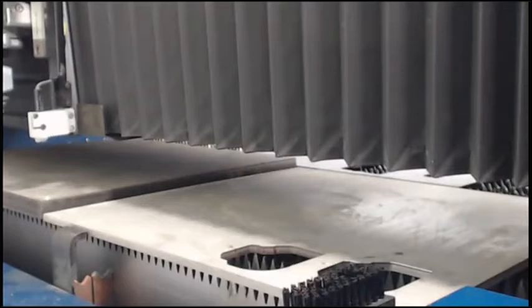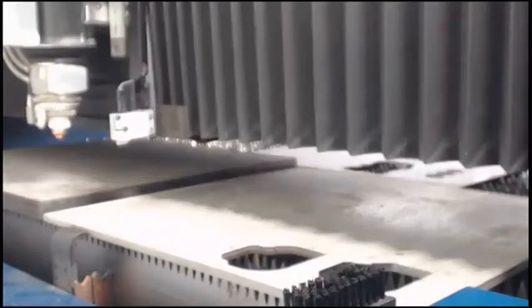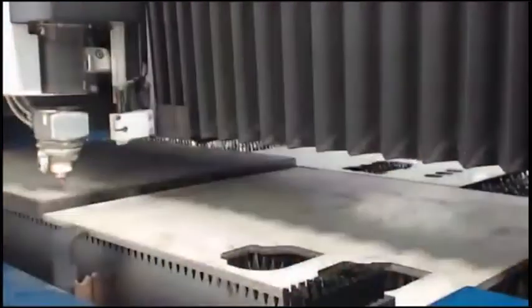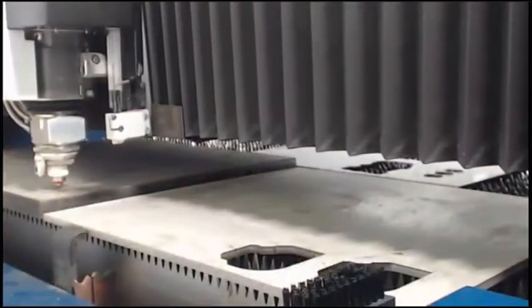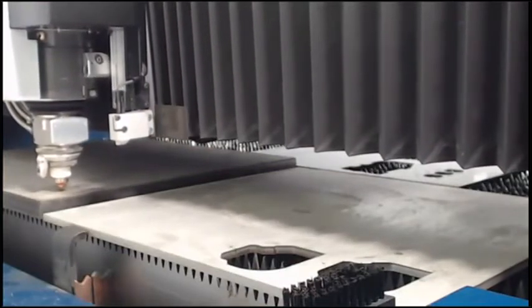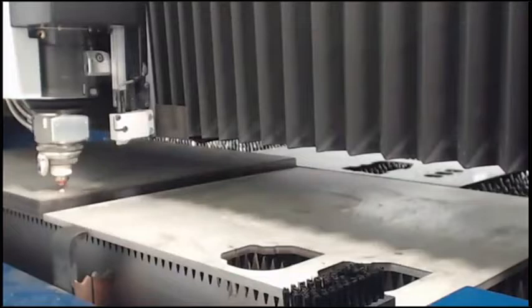And again, it's going to use this high-speed nozzle. So this is 1-inch 304 stainless steel. This is going to be cutting at 28 inches a minute, and it again uses 3-bar of air. Wow, it pierced in that time? It's almost through. That's its first stage, and now it's through.